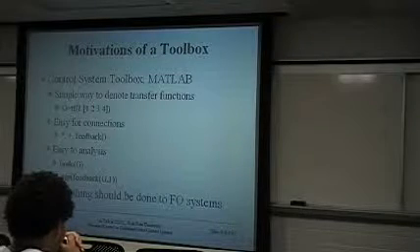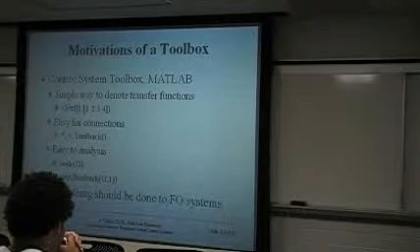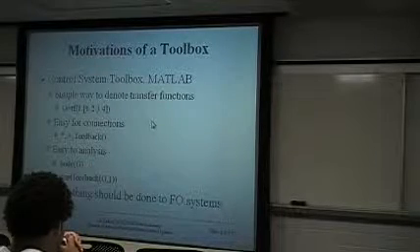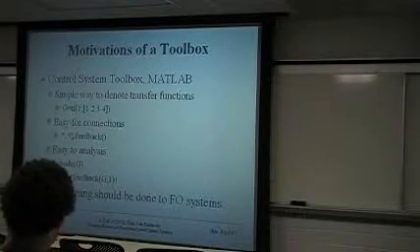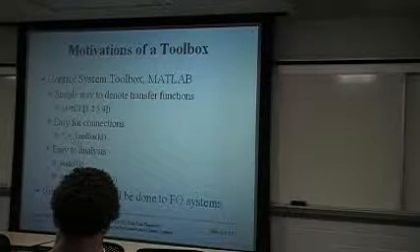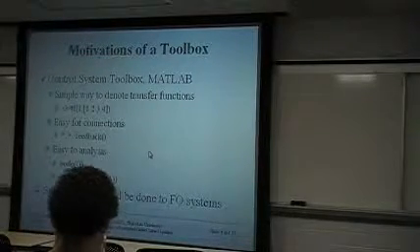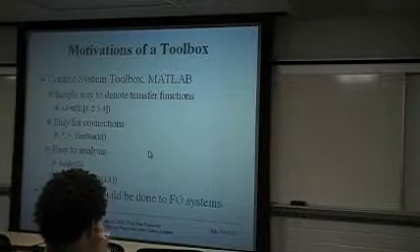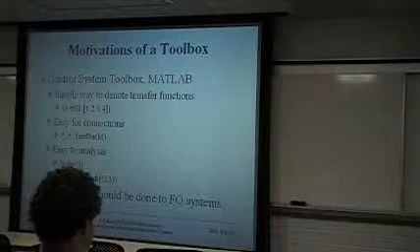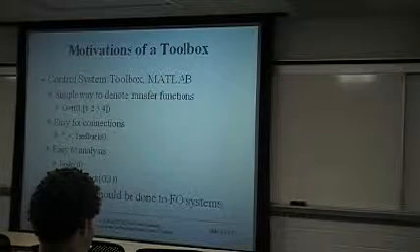In this toolbox, it allows you to represent a transfer function in a very simple way like this. And then you can use multiplications, plus, or feedback functions to define the series connections, parallel connections, and then feedback connections of transfer function blocks to form an overall system.